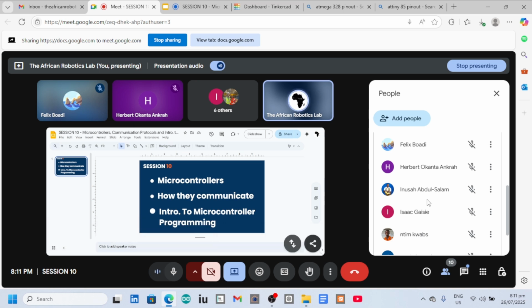And then we took a look at a switch, and yes, the switch is so common. We used it to turn on or turn off. And then we took a look at a resistor, and we got to know that sometimes you have a huge battery, like a 9-volt battery, but a component like an LED, if you supply that 9 volt into the LED, you may burn it, you may destroy it. And so we use a resistor so that it can resist some of the current or some of the voltage from the huge amount of energy going into the LED to destroy it.